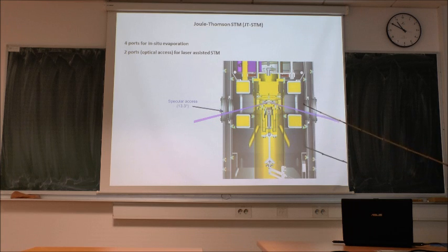So this is how an MBE is working, molecular beam epitaxy. So you deposit something and you get some layers. But if you deposit in situ, this means when the sample is cooled to close to liquid helium temperature, you will get individual atoms, you will get individual molecules, they will not agglomerate, so they will be individually there. In that case, you can study them, you can move them, and so on.